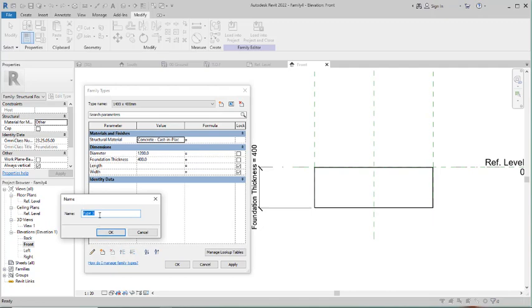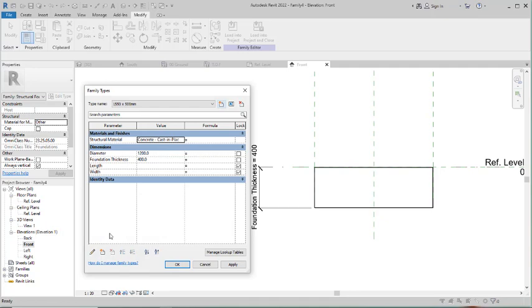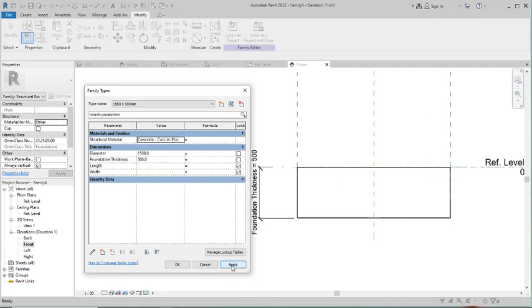Let's create another one, which is the final one, which is going to be 1550 like this, and then by 500 millimeters like this. Click on the OK option. With the same material, you change the diameter to 1550 right there, just like this. And then the depth of the foundation is going to be 500, just like this. Okay, so after which click on Apply successfully.